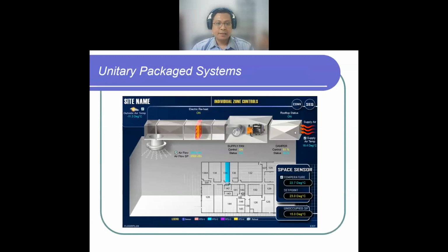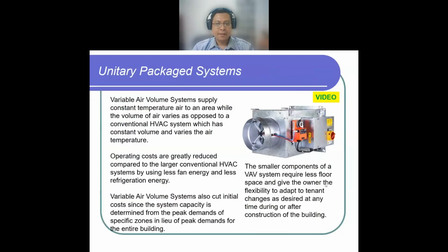Okay, you can see the 3D of the AHU system. If you want to see the AHU system, you can come into the Factory 3 building, and they have several types of AHU to serve several zones. Okay, this one is a type of VAV. This one is controlled by the actuator here. So the volume will be controlled, releasing how much air volume to the air duct.